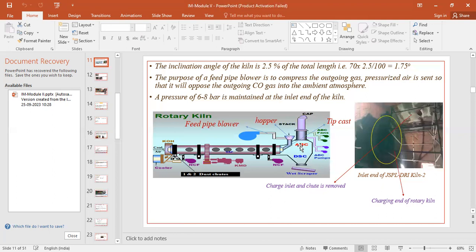At the ABC, that is the after burning chamber, there is a small inlet where unburned carbon or carbon monoxide, whatever is there, will be combusted, and the temperature will rise. Then the waste heat will enter into your waste heat recovery boilers, where the heat associated with that waste gas will be maximally utilized in converting water into steam, and that steam is basically used for power generation.